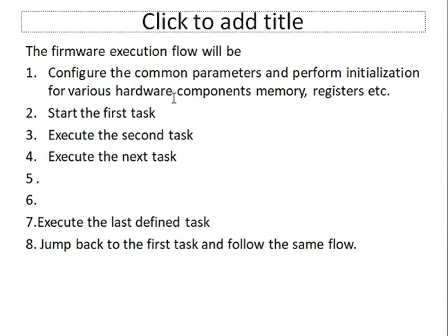After that, you require an initialization routine to be called. In initialization, the clock frequency can be set. Then you come up with the tasks. You start with the first task, go to the second task, third task if present, repeat till you arrive at the end task, then go back again and execute the first task.